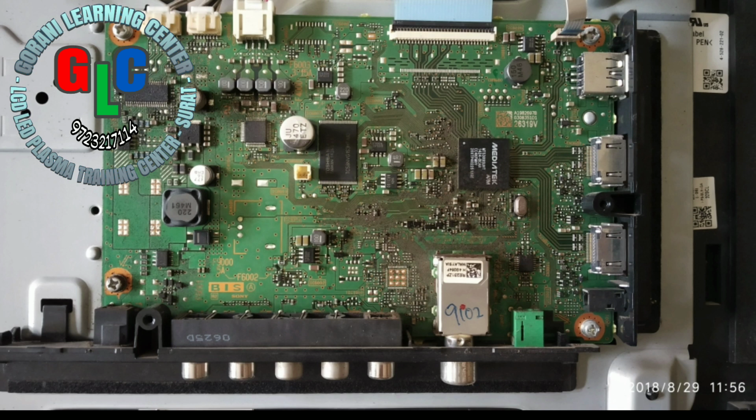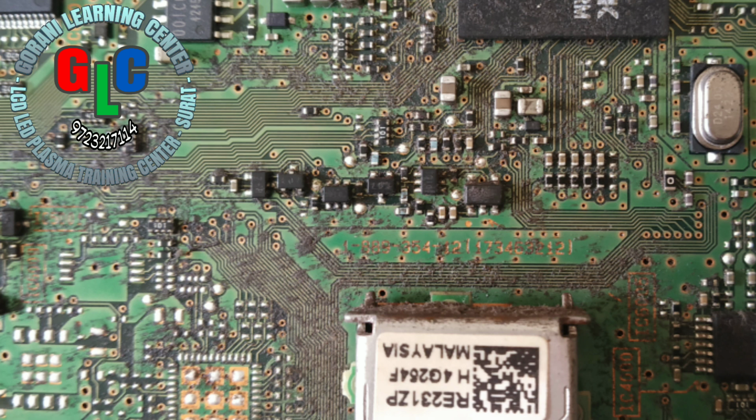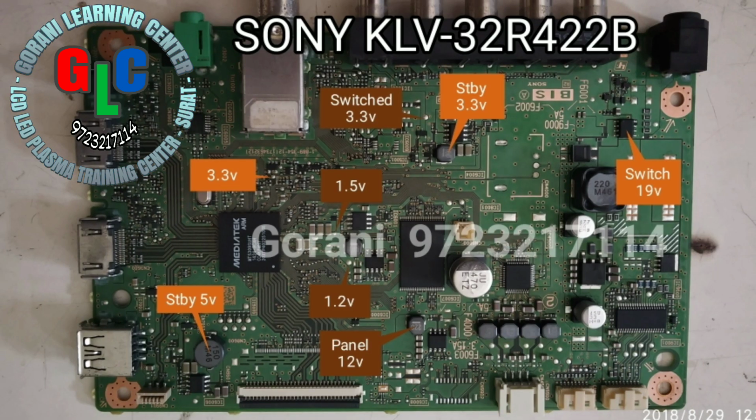Now we check the circuitry. Open the set and check the main board carefully and closely. It seems rusty or moisturized. This may be a problem, but the main thing is the feedback reference of main power. Now we check the main power error section. First we check all related voltages on this board for abnormality. All supplies are found okay.